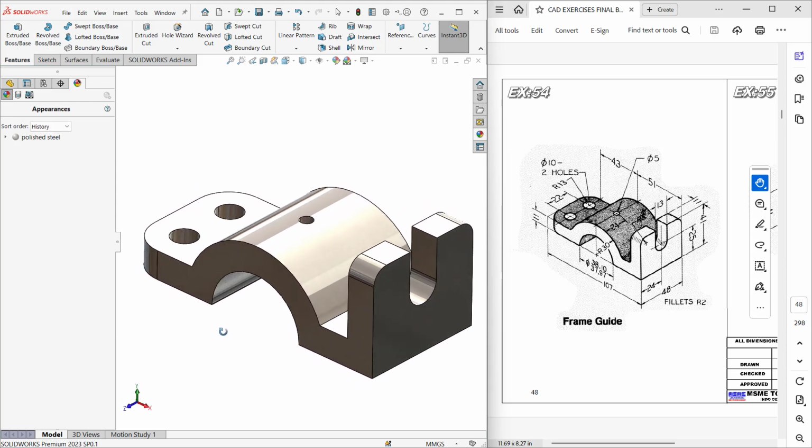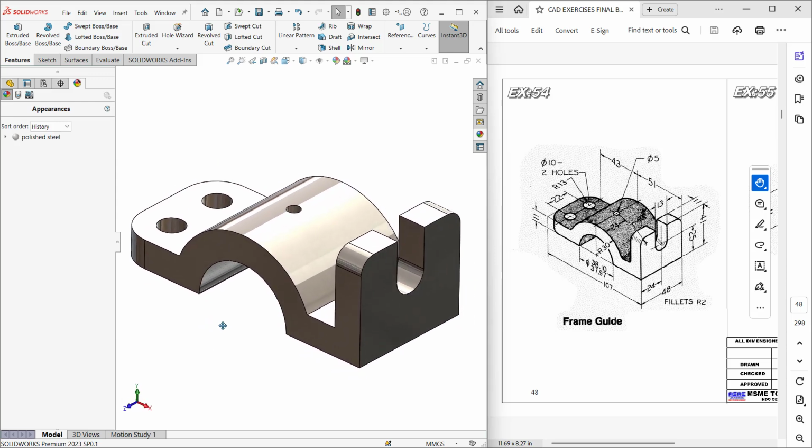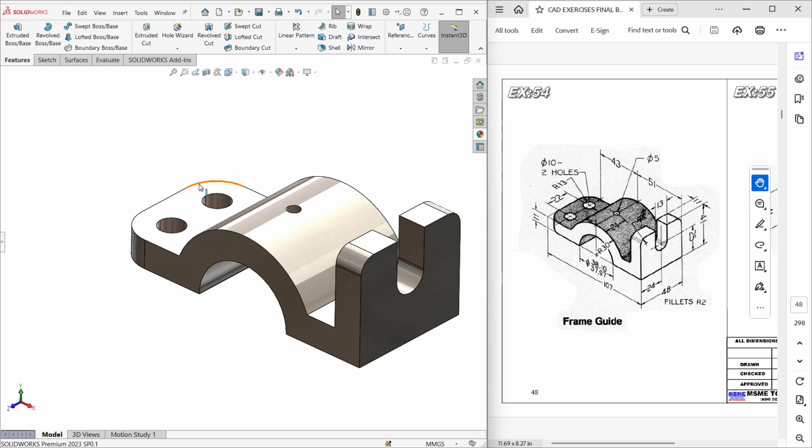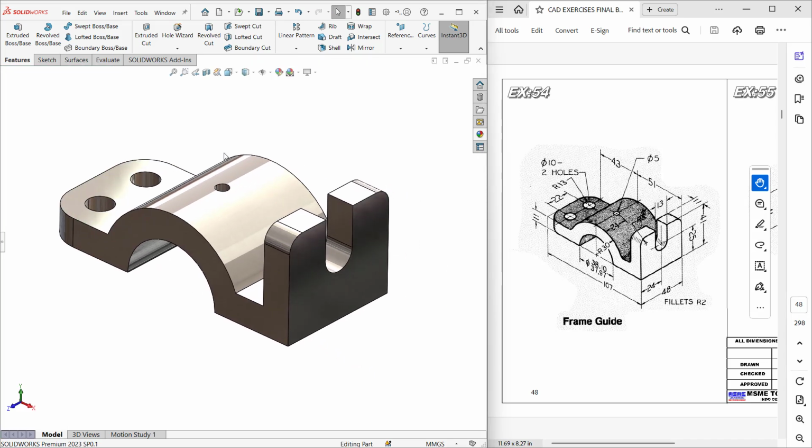Yeah, now once you're done with this, I just wanted to introduce the drafting workbench. Let's take this model into account and try to do the same. What you can do now is create the drafting for this directly. What you do here is directly switch from here. There is an option, make drawing from this part directly. So instead of saving this model and again bringing it into the drafting workbench and trying to do everything, this is a shortcut.